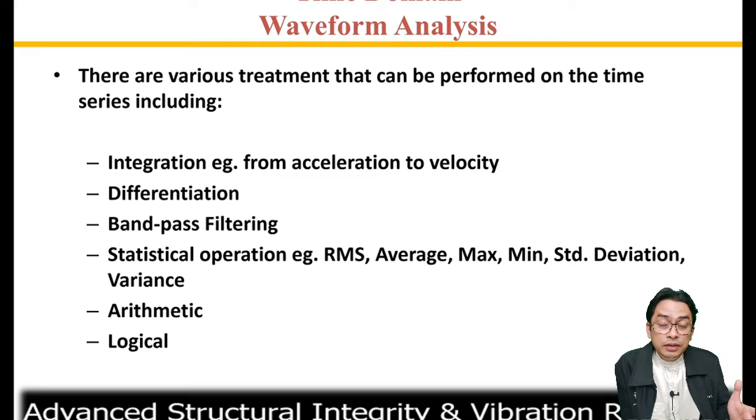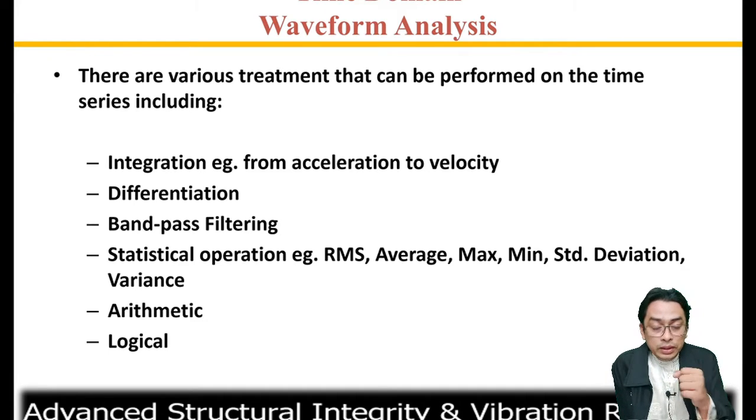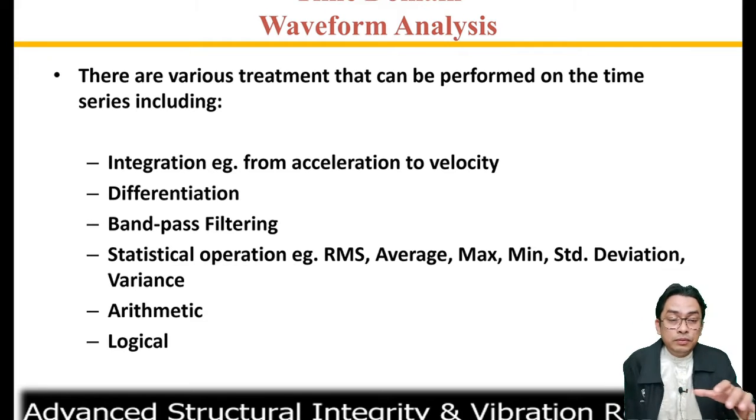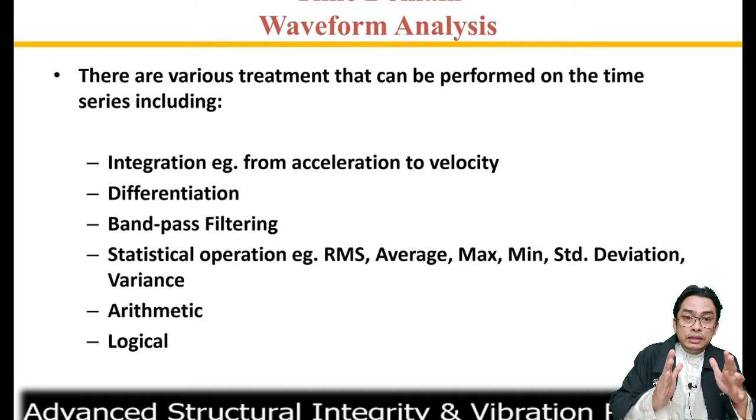The band pass filter. We already saw the low pass filter in the anti-aliasing. We already understand a little bit about the filters: for the low pass, we only allow low frequencies to pass the filter. The same goes for the high pass, which allows signal frequencies higher than the cut-off frequency. Then band pass is the frequency in between, and stop band is where we only allow the frequency beyond the cut-off frequency.